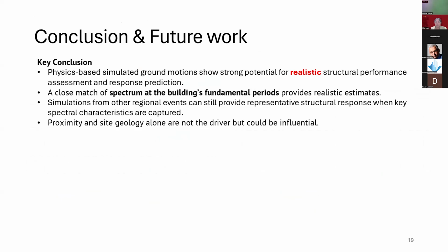So to end, the key conclusion: we can use SGMD to get realistic structural responses. It is opening up a very good paradigm for us, very good space for us to do structural assessment. We need to make sure they are close to fundamental periods when we are doing the spectral matching.